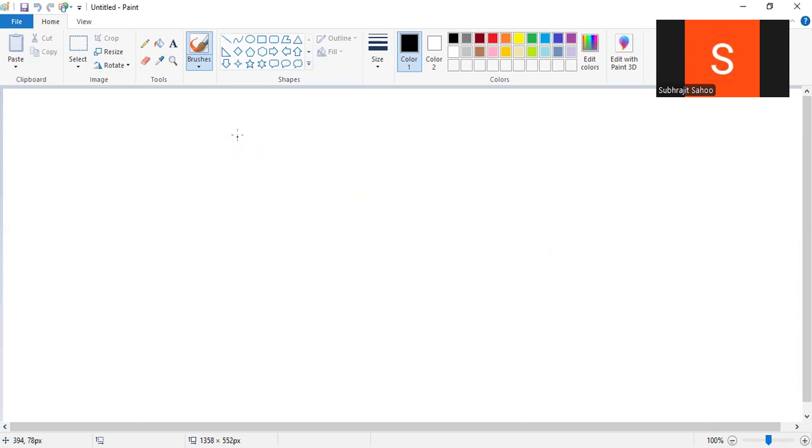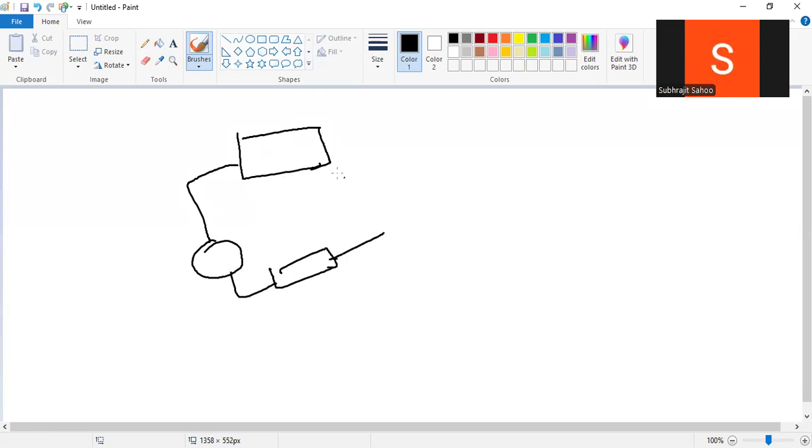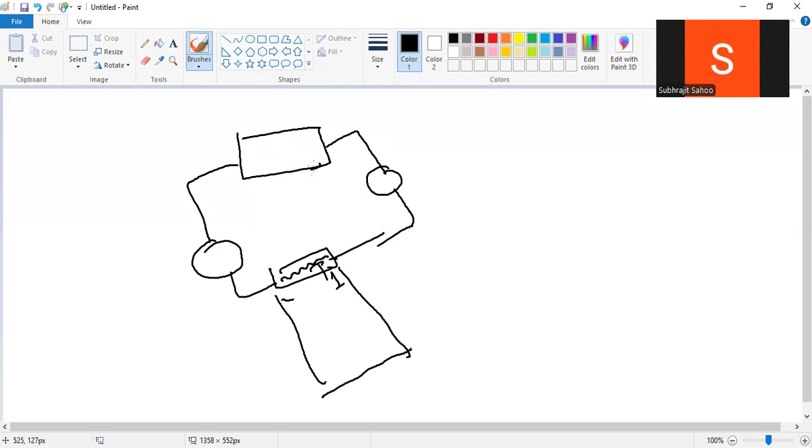Observe, this is my condenser and this is the expansion cylinder, this is the evaporator, and this one is my compressor. This is inside, and the temperature here, where air is flowing, refrigerant is flowing, is T1. Here also refrigerant is flowing, temperature is T2. What you told, if T2 decreases, then COP will increase. Because this is high temperature, from the compressor it is coming, pressure is more, temperature is more.